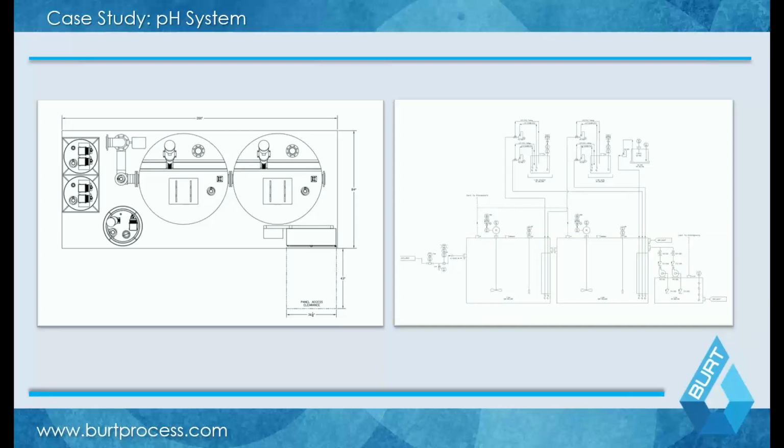Now, Mark, when would you recommend changing from a single stage system over to a dual stage system? That's a good question, and it does depend on what type of system you're utilizing. Typically, most people say it's based on flow rate, but it's also based on how the system is designed. Typically, smaller flow systems, if you're in more of a standard chemical range, can operate as a single stage system. Once you get into a higher flow range, or you end up with more extreme waste conditions, you do tend to go to a two-stage system.